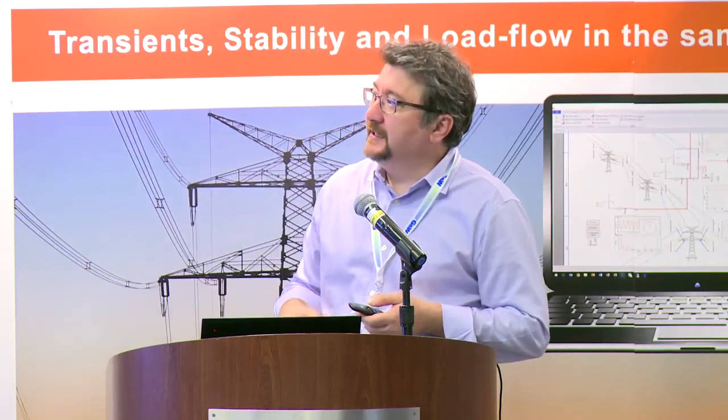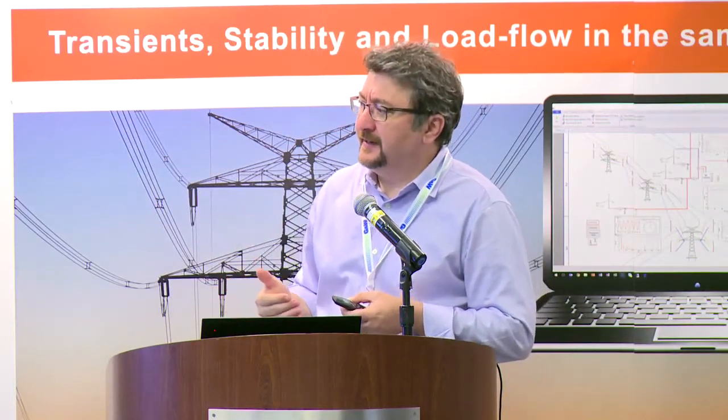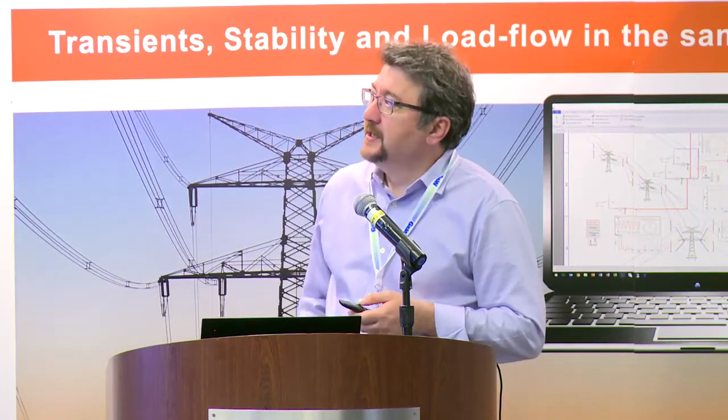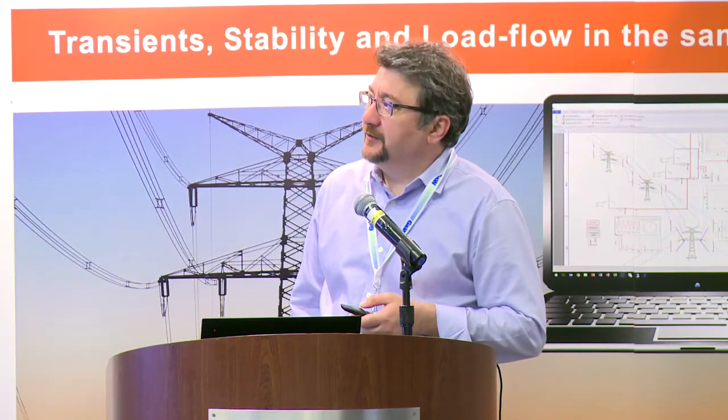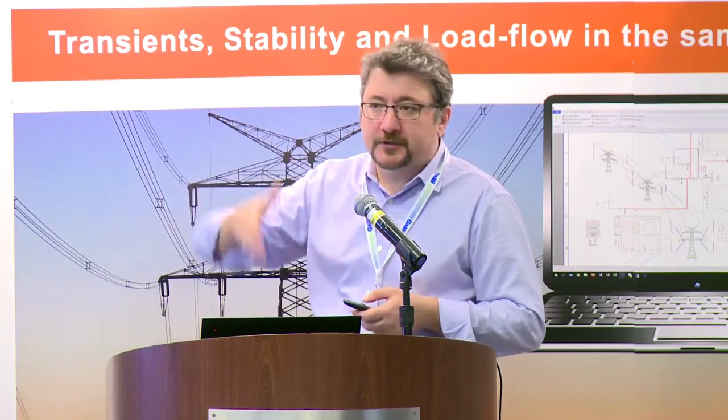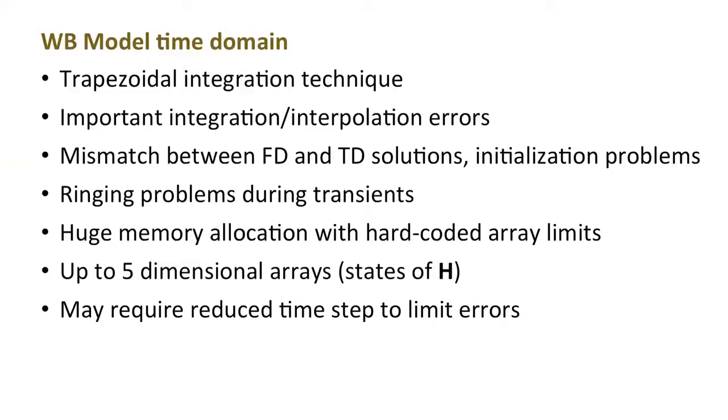So in time domain, how do we do the solution? We have these transfer functions of the line, and I need to solve them in time domain and integrate to my circuit, right? So how do I integrate to the circuit? It's like a current source. It's a Norton branch, actually. I think almost all models in the industry use either the trapezoidal integration technique or Euler backward.